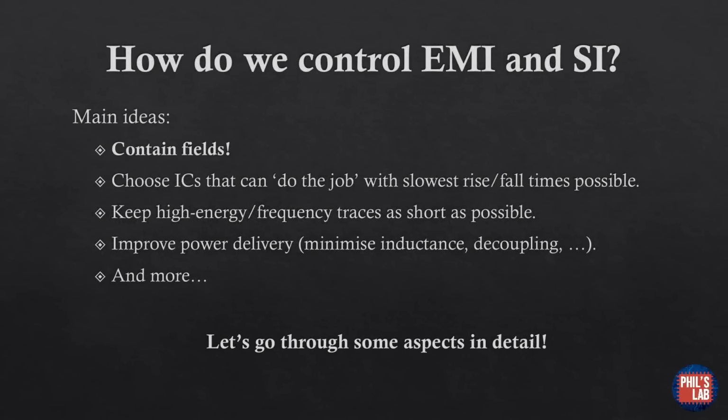Before we get to traces, let's briefly talk about how we control EMI and signal integrity from the slides and information we just saw. The main idea is to simply contain fields. We saw that all of the energy is stored in the fields between the dielectric or in the dielectric space. So this is our main job as PCB design engineers.